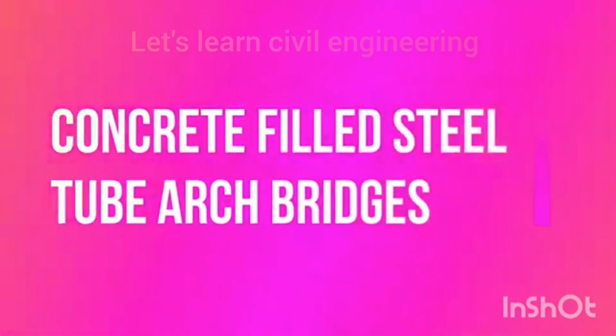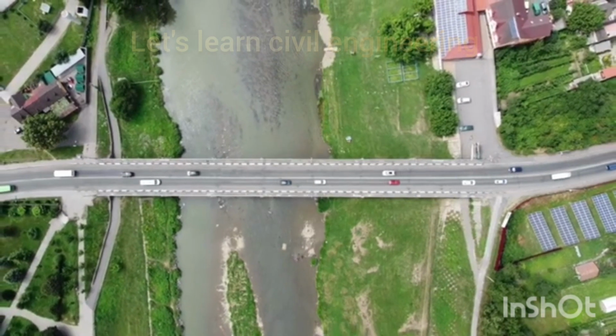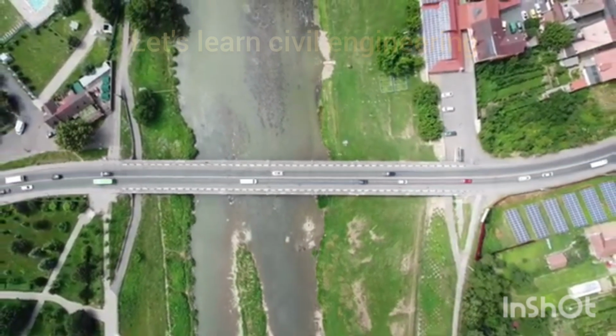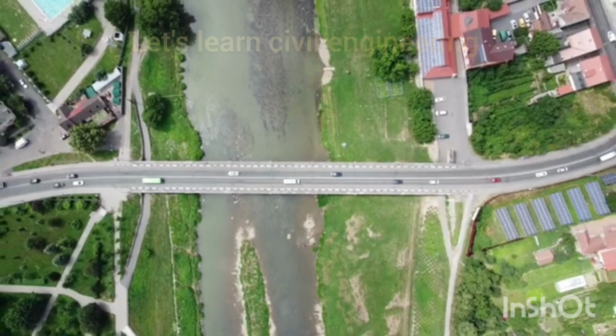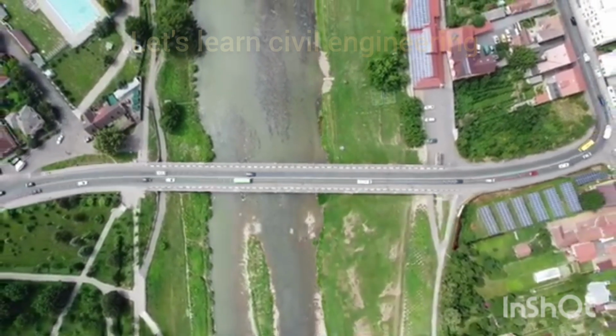Concrete-filled steel tube arches. In this type of bridge, a steel tube skeleton is covered with concrete to form a composite arch. This is one of the most remarkable implementations of composite arches. The steel tube arch acts as the skeletal system during construction, thus simplifying and facilitating the construction.